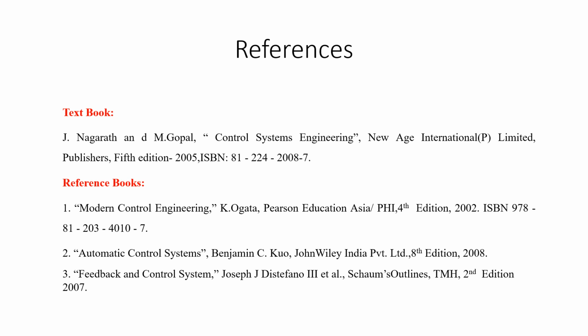The most important factor that we need to consider in the block diagram representation is that simple block diagrams can be very easily reduced using the reduction rules, but when we come across a complex block diagram, it is very tedious to apply the reduction rules to evaluate the transfer function. To solve this problem, next we have taken another technique where block diagrams were represented using the signal flow graph.